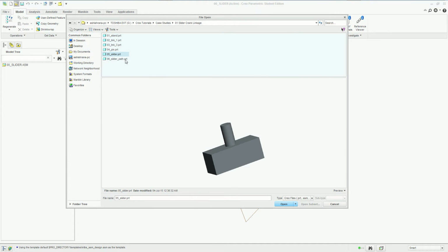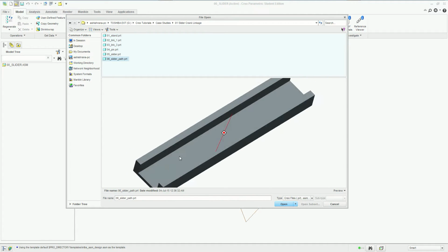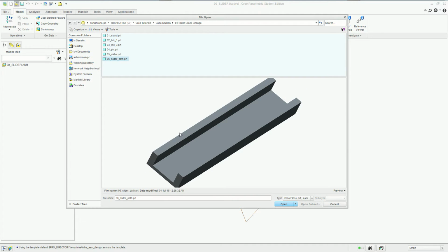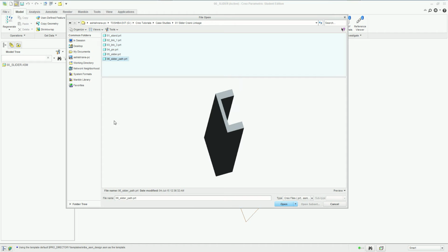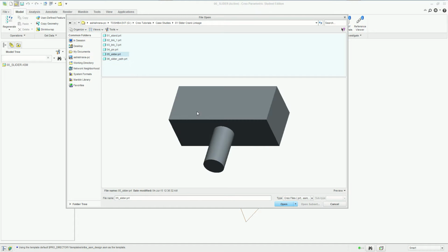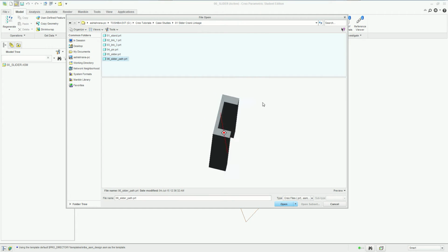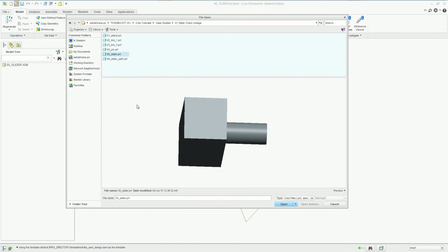And then we have a path for the brick to slide in, and that's what this is gonna serve as. It's a very simple part. Again, just make this shape and extrude it outwards. Not very complicated at all. Just make sure you dimension things properly. Make sure the path, so this distance right here, when you make this shape, this distance, this gap, should be the same as the width of this brick right here.